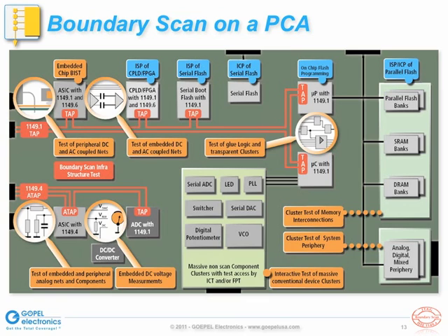The first type of test that typically is executed anytime someone is running boundary scan tests is a so-called infrastructure test or scan chain integrity test. The infrastructure test verifies that the scan chain is functioning properly and that the correct boundary scan devices are mounted on the printed circuit assembly. If the scan chain does not work properly, there is typically no point in executing any other test since the test vectors couldn't be delivered.